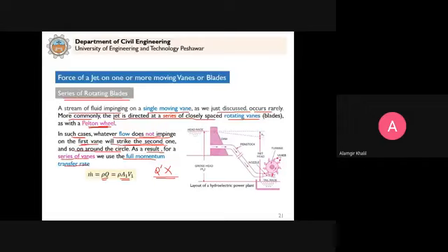It was reduced for a single vane. Because if this vane is moving and it misses some discharge, the second would come. This is how the design will work: we have to provide the vanes in such a way that if the discharge misses one blade, the second will come and hit that discharge. So that's why we do not use Q dash, but for a series of vanes, we consider the same discharge in calculating the force. Clear?